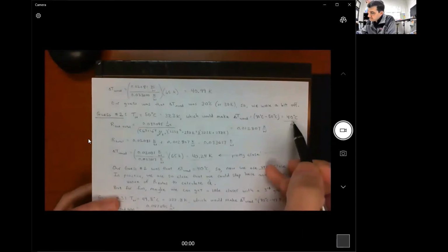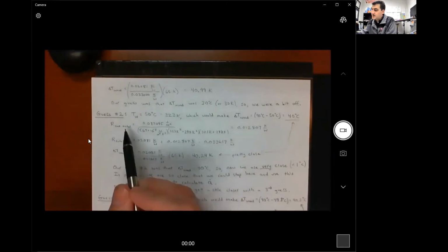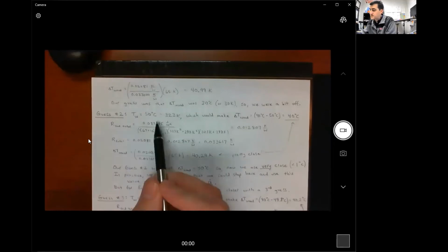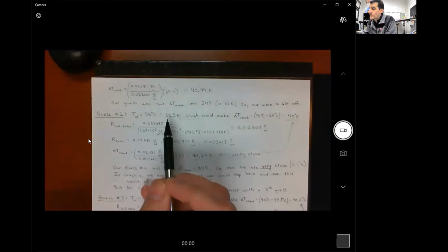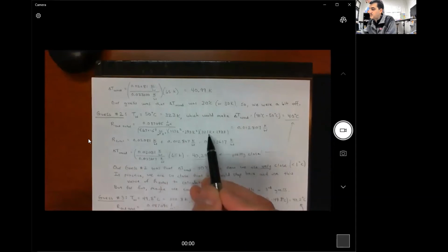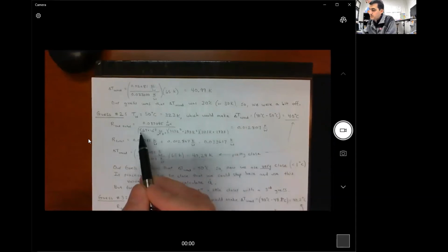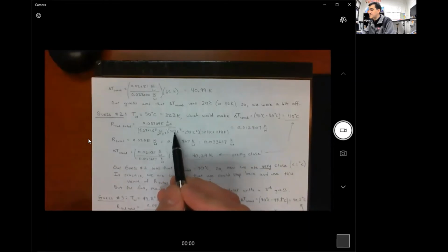Okay. So now we go through the same calculations that we just did, not all of them, but now we just have to calculate R rad total again. All right, so don't calculate the surface and space resistance again. That's the same. That's not going to change. The only thing that's changing is our temperature for the wall of the barrel right here and right here. So I plug in for the Stefan Boltzmann constant right here. This is the temperature, the new assumed temperature of the outside of the barrel.